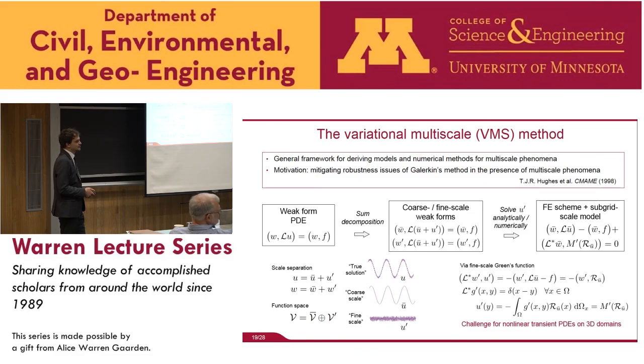In your micromechanically motivated modeling, if I understand well, you really look at material linearity and the problem is geometrically nonlinear, because you are looking at creasing and buckling, but all the homogenization technique is based on elasticity. So I'm wondering if you had to consider yielding. At what scale would you operate, and how would you do it?